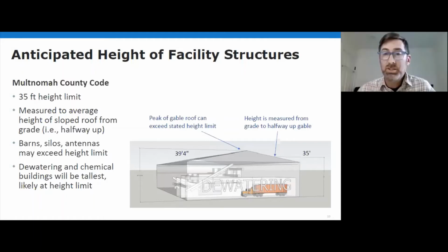It's a good question. Multnomah County Code measures decibel levels from a sound source at the neighboring property line. So for the closest neighbor in Multnomah County, that sound will be measured at their property line. It's a little different for folks in Clackamas County, where the decibel level is actually measured, I think it's 3 feet from outside of a window that contains a dwelling unit.